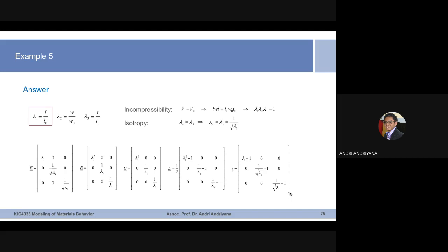In the case of tensile load, you can imagine it: it is simply the change of length over initial length. That is the significance of engineering strain in uniaxial extension. But in more complex situations of multiple loading, where you ask what the strain is along 1, 2, and 3, it becomes a bit more difficult. But the idea is that for engineering strain, it is the change of length over initial length.